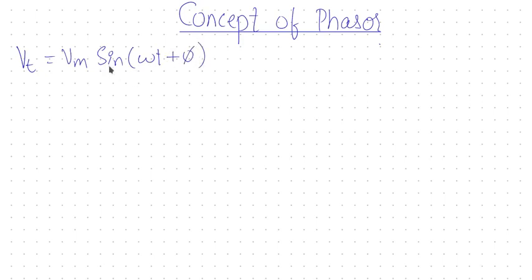Note, whenever you're discussing signals, you can either choose sine or cosine. Be consistent with your notation. Always use one type, either sine or cosine. If you use sine but the question is given in cosine, what you can do is always change the phase factor. Now, a shorthand way of representing the same thing would be Vm angle plus or minus phi. This can be plus or minus.